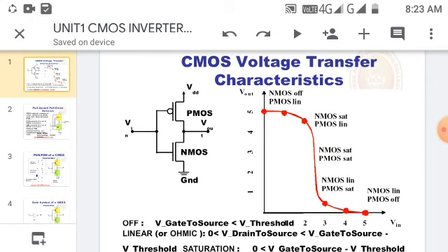We have a bubble in PMOS. So the output of PMOS will be 1 because we are giving the input 0. So the output will be in 1 condition. Whereas in NMOS, we are giving 0, and the output will be 0. So the PMOS is connected to VDD and NMOS is connected to ground.